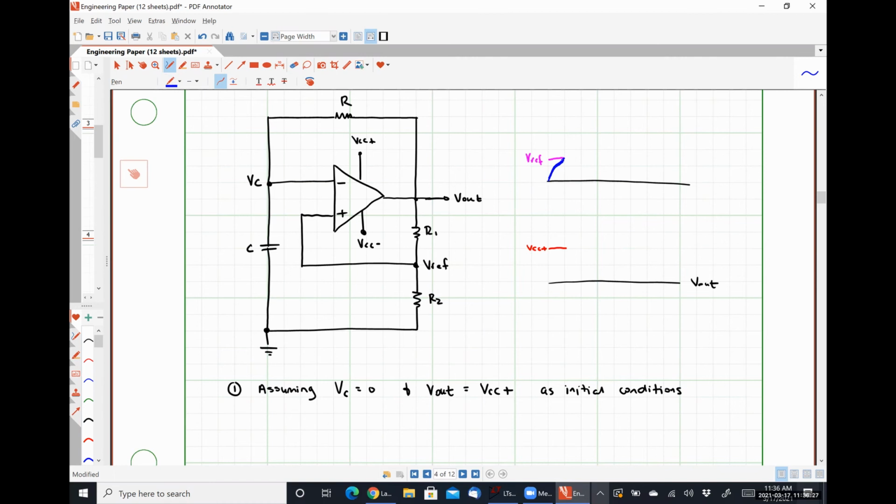And it's going to take time to do that because this is an RC circuit, right? So it's not going to instantaneously jump up there. It's going to follow the time constant, R times C, and it's going to take that long, or actually 5 time constants or so, to get close to charging. But the rate at which it charges is based on the time constant.